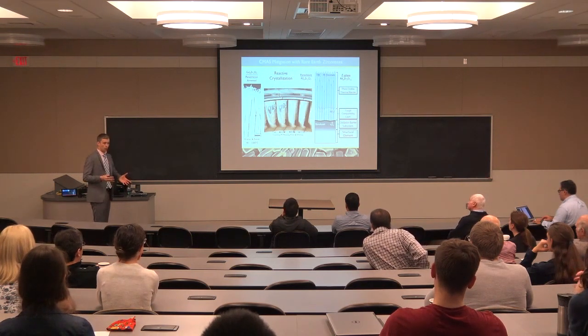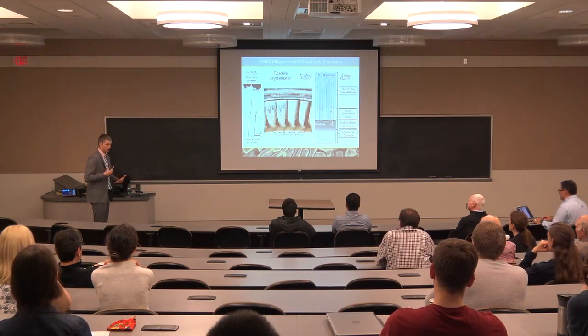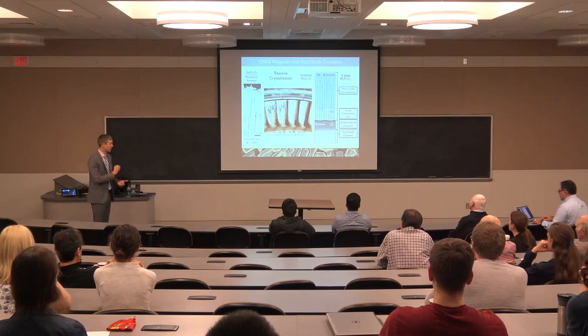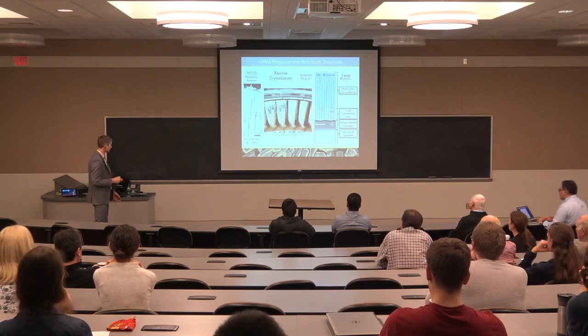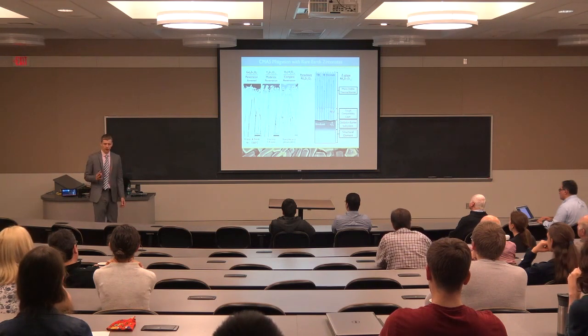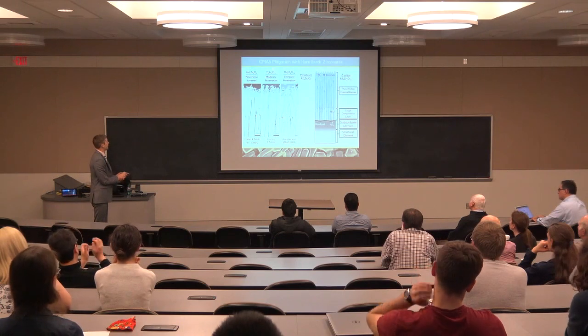The base system has a lot more rare earth in it, and the apatite crystallization within the structure prevents the infiltration, and the coating survives, even though the toughness of the gadolinium zirconate is a bit lower. But the problem is that it doesn't work equally well for all rare earth cations. It works really well for gadolinium.